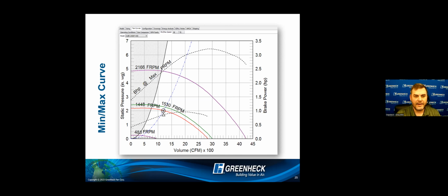Say you've got a mechanical garage, a city garage, right? From 8 to 5, I need to move 600 CFM. I'm making up numbers, folks, but I need to move 600 CFM just because people are in the bays. Now, I have a carbon monoxide detector that's going to send this exhaust fan to max air movement if it is in alarm state, right? If someone pulls a truck in, that truck's still running, I've got carbon monoxide everywhere, and I've got people working on them, I need to bump up, move max speed.